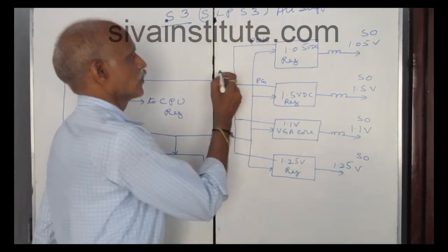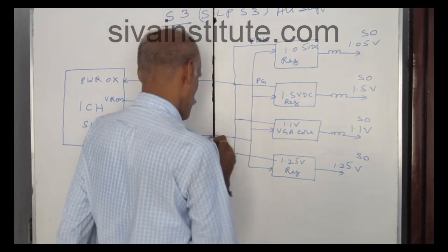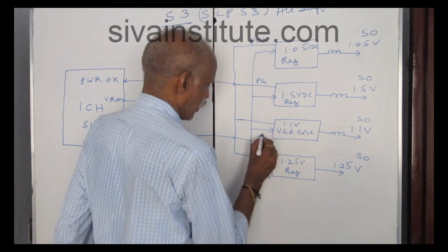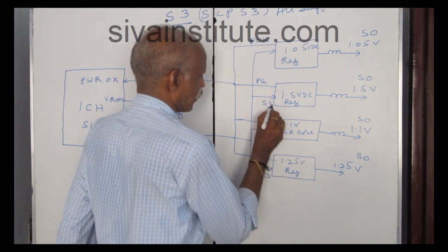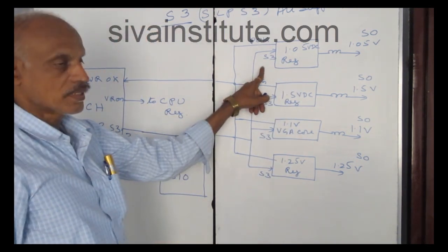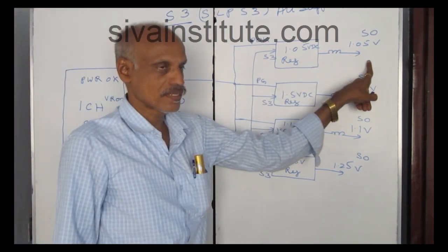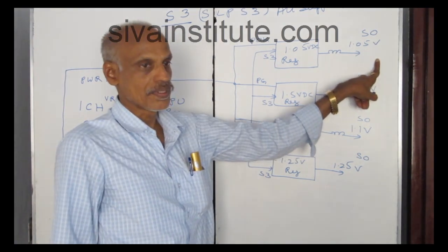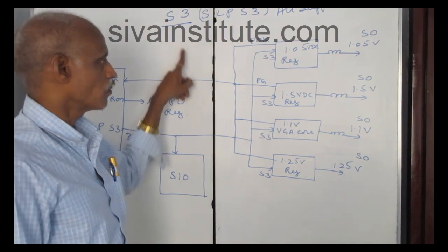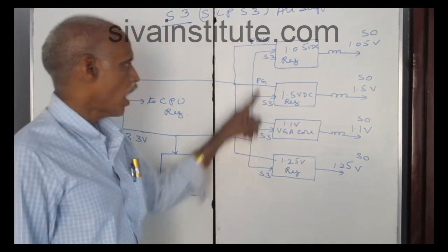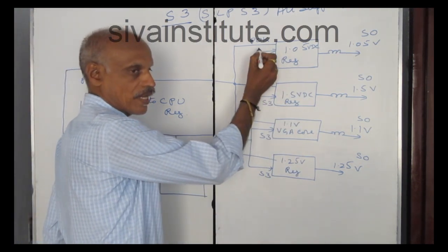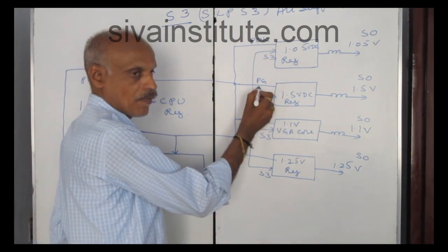When you give this S3 command, when you give S3 3.3 volts, this output voltage comes out from this IC. This is S0. S0 means run power. This SLP S3 goes to all regulators. When all regulators are okay, these regulators release POK, power OK, or PG, power good.